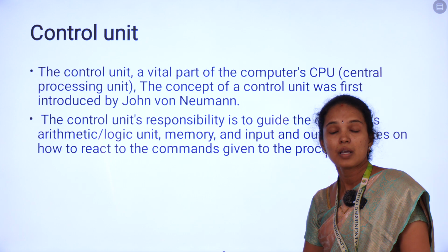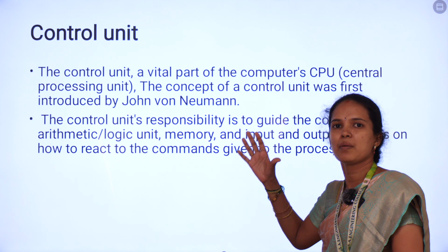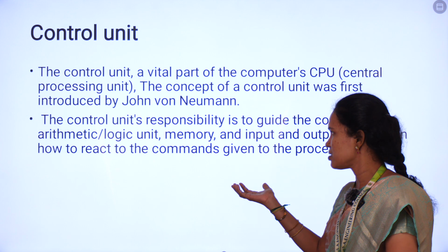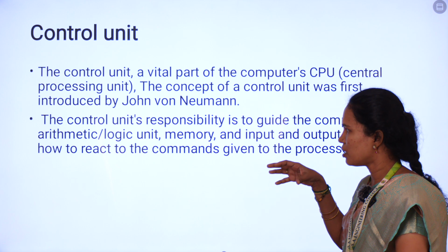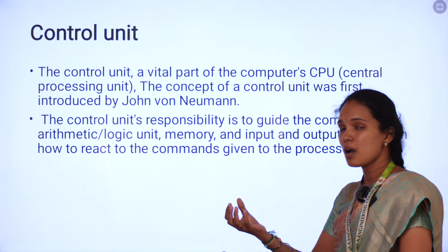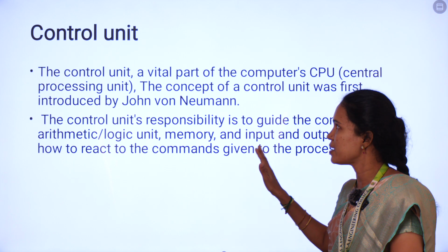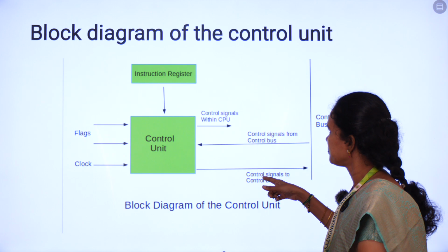As I told, all the other components will activate only with the help of control signals. Without getting control signals, whether it is a register, memory unit or ALU, nothing will be activated. How to react to the command fetched by the CPU is based on the control unit only. That's why it is called very important.